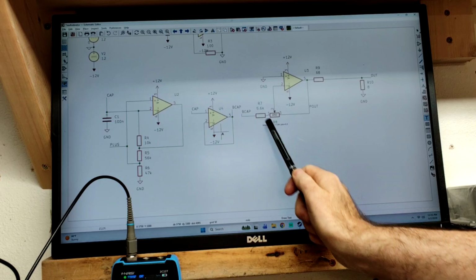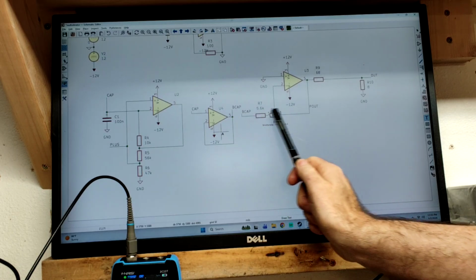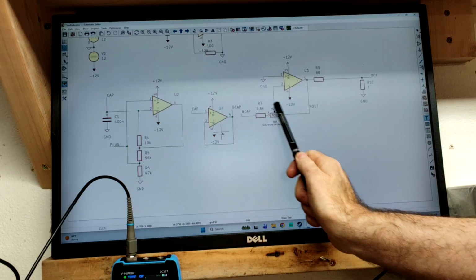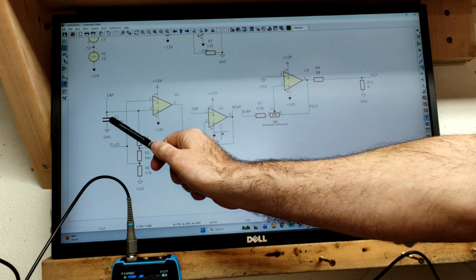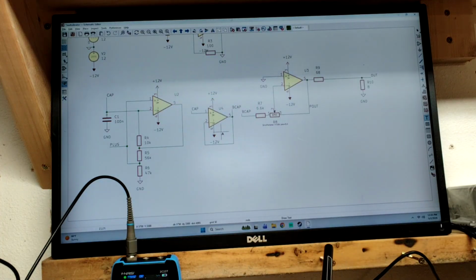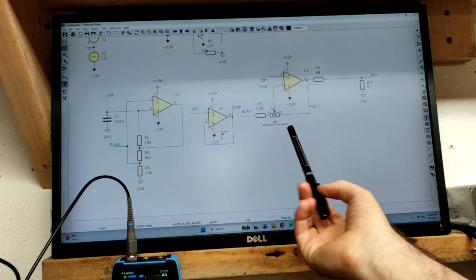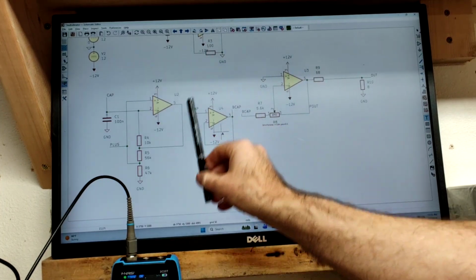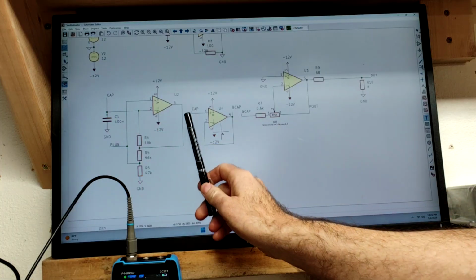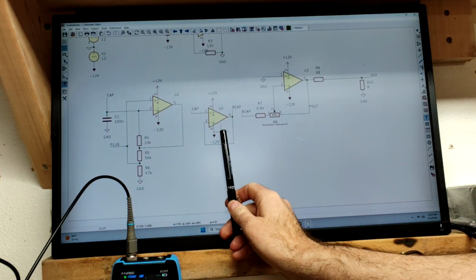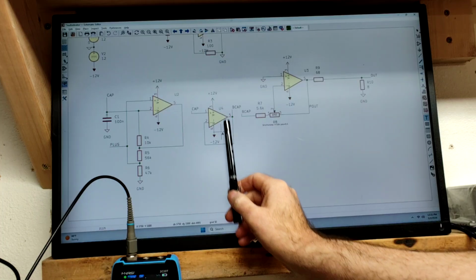And so depending on where I put this potentiometer, not only is it going to change the amount of amplification on this circuit, but it's also going to drain or source current to the capacitor, which is going to change the frequency. So what we need is a buffer in between. And so now we have this cap coming to this little buffer circuit that looks just like the one we saw before with the voltage divider to create that ground.